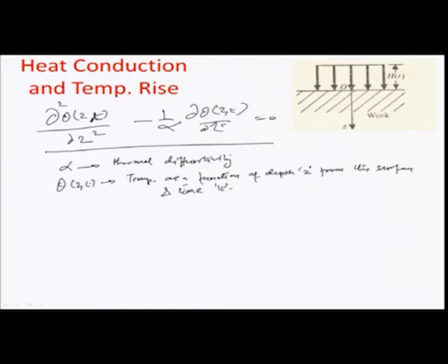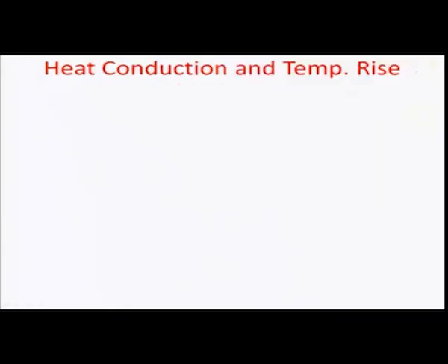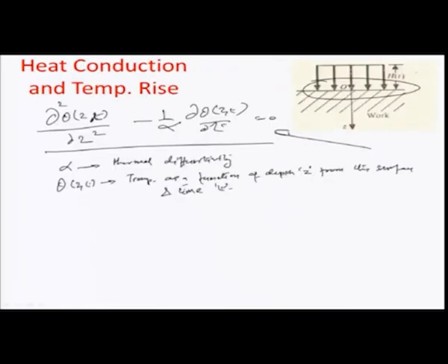We apply some boundary conditions for estimating this equation on this beam workpiece interface, assuming that there is a constant heat flux which is coming through the laser beam into the surface, into the work material.